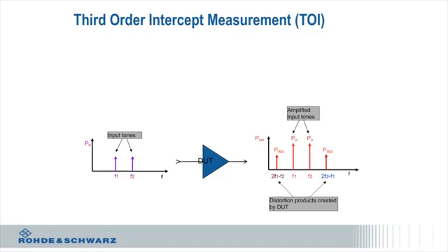When you go back and look at the noise figure of an amplifier, things that typically have very low noise figure, or add very little broadband noise, typically have lower intercept points. So you have to use that cascade analysis to actually determine what amplifiers I put where. And this is really kind of the magic sauce of RF design.